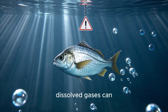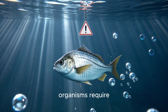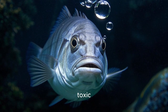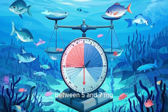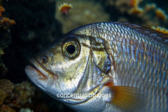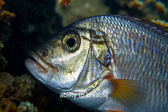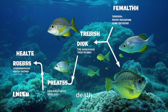First, excess dissolved gases can be toxic. Most fish and other aquatic organisms require dissolved oxygen for respiration. However, if the concentration gets too high, it can actually become toxic. For example, most fish species need between 5 and 7 mg/L of dissolved oxygen to survive. However, if the concentration goes above 9 mg/L, it can actually start to affect their gills, causing damage and impairing their ability to breathe. This can lead to stress, decreased growth, and even death.